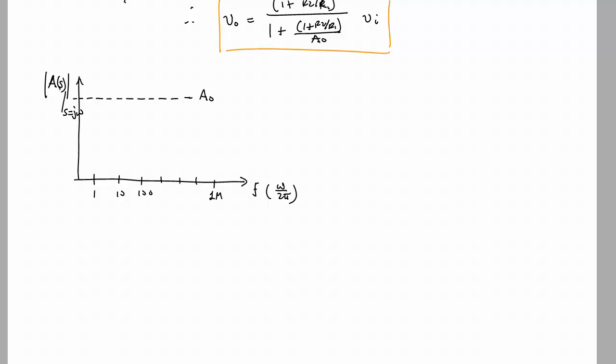And what we find is that op amps are designed to have, at low frequency, a flat gain that is frequency independent, and they'll call that A naught. But then they actually start rolling off at a constant slope. It's supposed to be a straight line there. And so it's a slope of -1. In other words, 1 decade in gain for every decade in frequency.